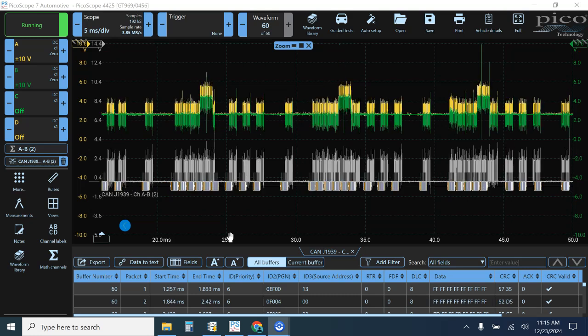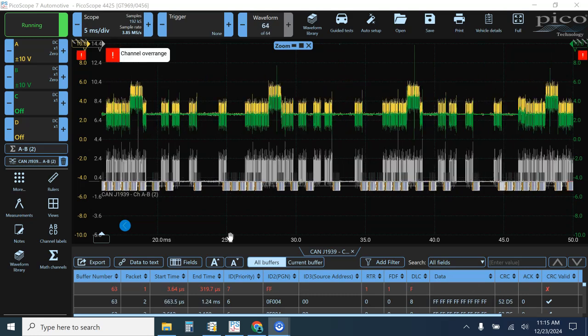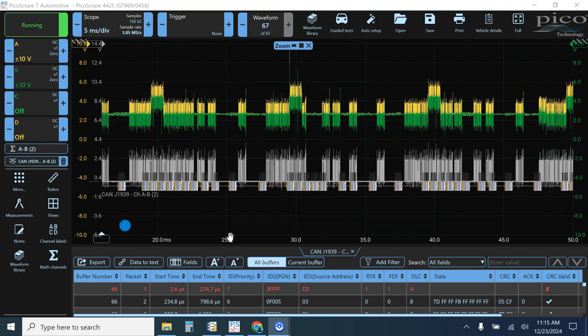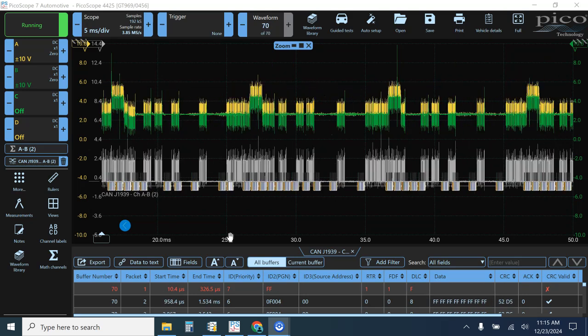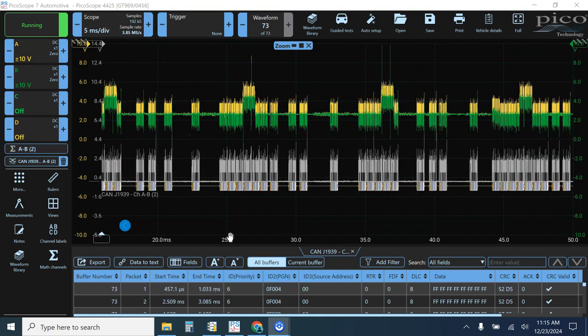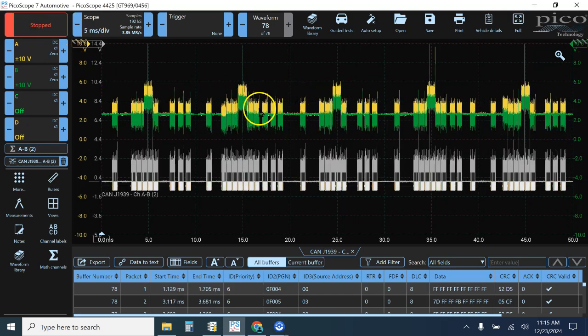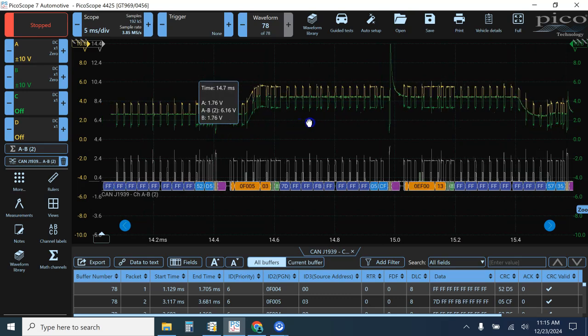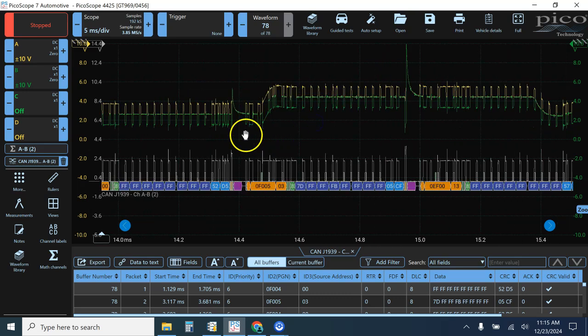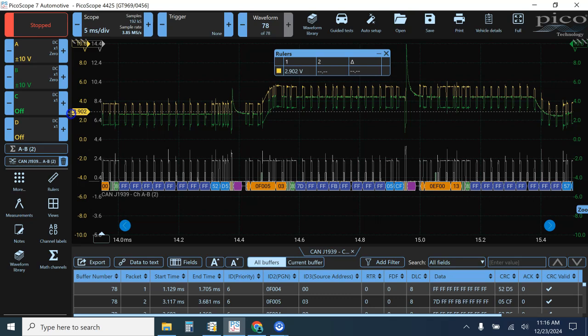Okay, so this is the same machine. The only difference now between this and the last display is that I've reduced the resistance from a couple hundred ohms to about 10 ohms that is on the ground for the knock sensor. If we look at the data, we're getting some pretty strange patterns here. If I look at some of these messages, I can see that this is the transmission controller, and partway during the start of the transmission, we can see this swooping up and swooping back down, which is really kind of strange. So if I look at where my voltage center is, here's my 2.5. I've got this increased up to like 4.3 now.